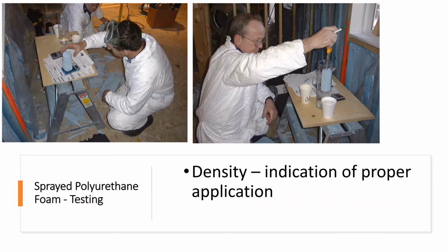Now, one physical test you can do with spray foam is something called density testing. That density testing is going to give you a number that you can compare to what the manufacturer says it should be. And if it's within that range, you know it's been processed and mixed right. So we don't have that with fluid applieds. Spray foam, we actually have it.